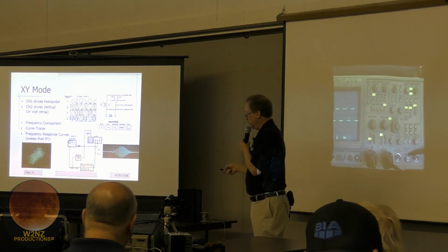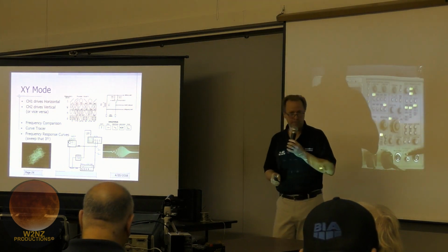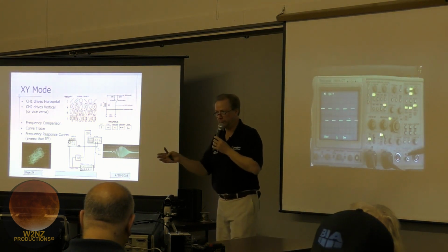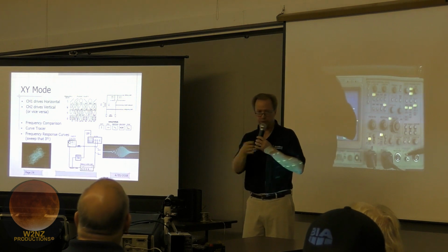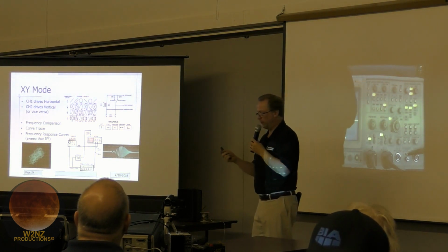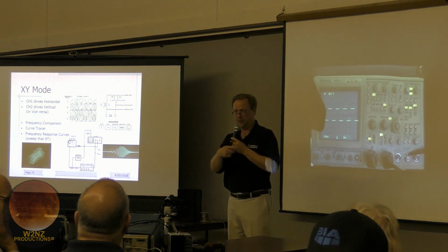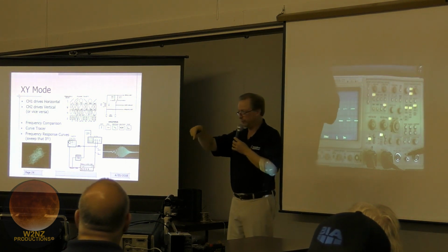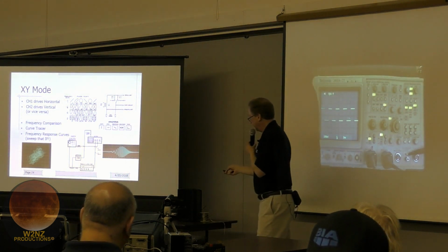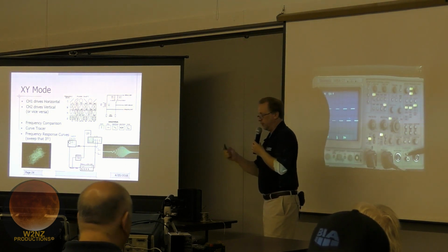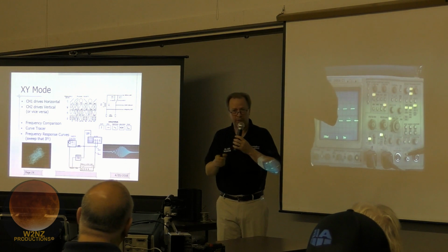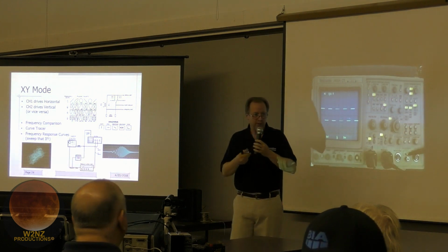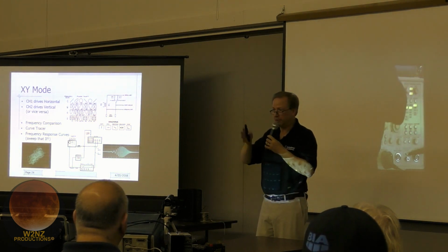Now, another interesting application is sweeping an IF of a receiver. Let's say I have a sweep generator that's sweeping through 455 kilohertz, maybe plus or minus 50 kilohertz or something like that. And I'm sweeping this frequency coming out of the sweep oscillator. Now, what if I drove the X position of the trace by a voltage that corresponds to frequency, and I plotted the response? Now I can actually build a display that plots out the filter bandwidth, the filter characteristic of the IF. Now if I want to align it, I can adjust the alignment slugs and things like that to maximize that. It's an interesting way of tuning and aligning a radio instead of just looking for maximizing a particular signal.